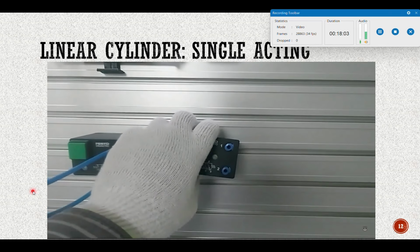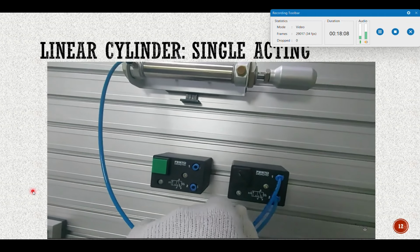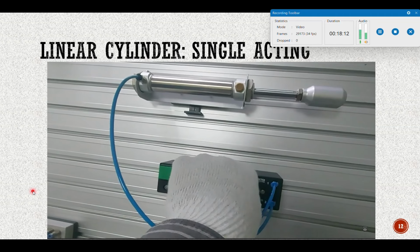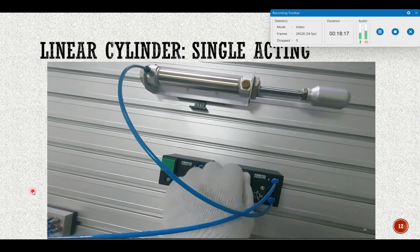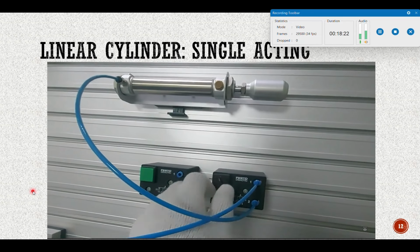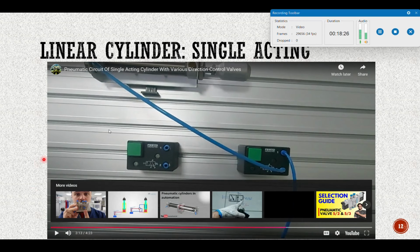Now we'll change it. How it will work, we'll see. Again, direction control valve with selector switch. The function will be the same, but if you notice, the operator changes. So based on the purpose or application, you will change the valves, whatever function or application you are looking for. If you have a push button, you need to hold that push button. Once you release the push button, the valve will be retracted.